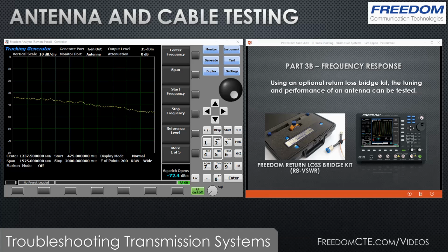The way we will do this is to look at the frequency response using the tracking generator, and we are going to need a return loss bridge kit. We're going to need the ability to isolate the reflected power to feed it back into the instrument.